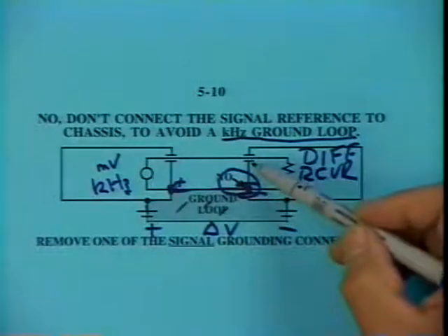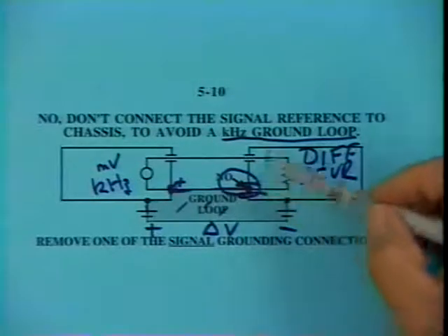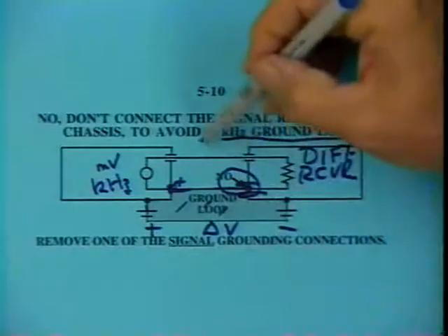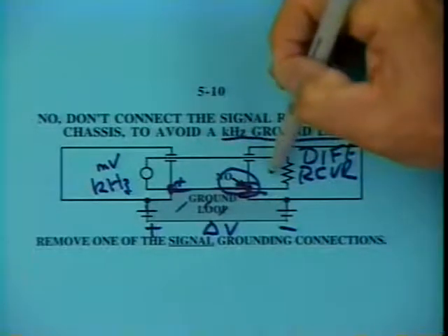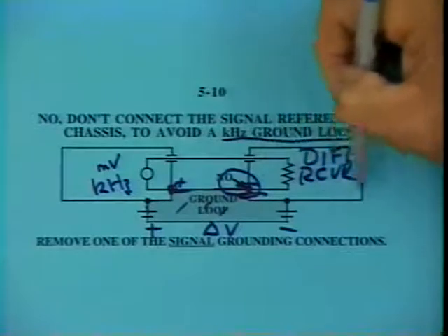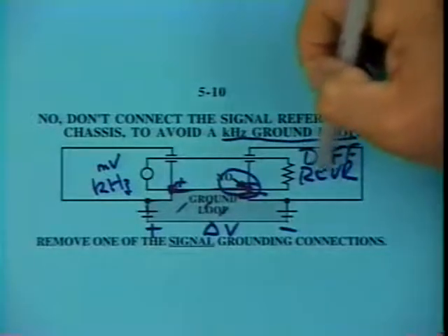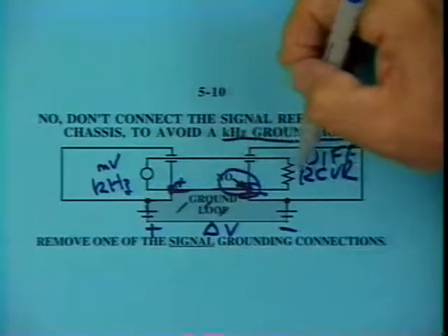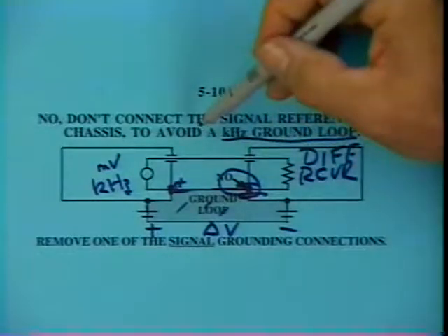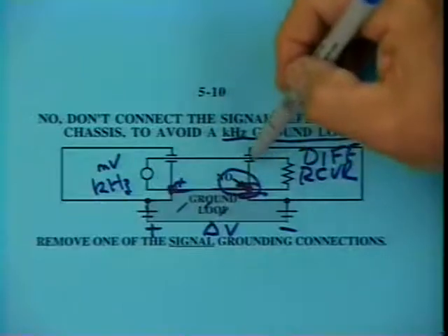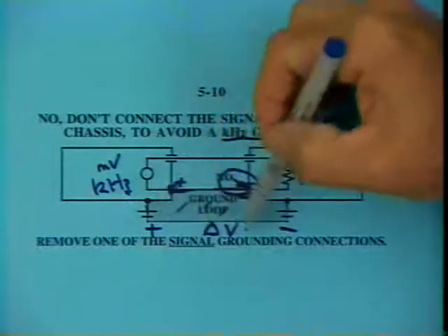Capacitively couple both of these leads to the box. That'll help us reduce electrostatic discharge energy from coming in. And if there were some digital circuits over here in some part of this equipment, that would help reduce high-frequency digital circuit signals from being emitted. But we avoid the metallic connection, and that avoids the low-frequency ground loop problem.